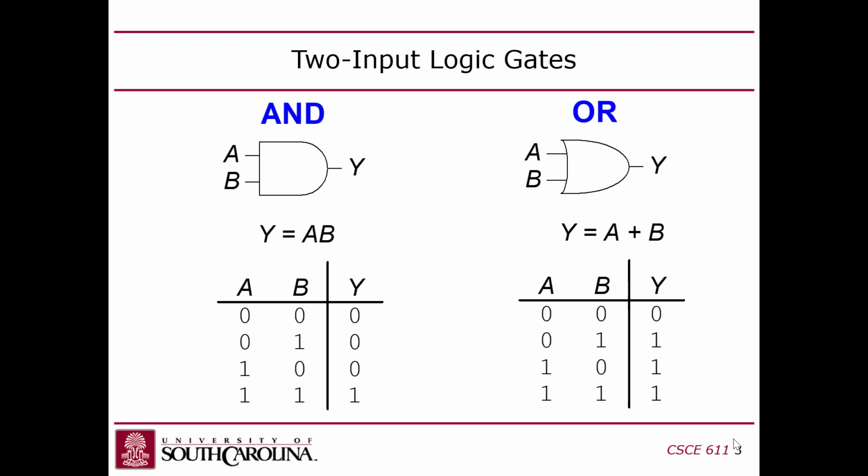You can make any kind of gate you want, right? Now these AND and OR gates just define the specific truth tables for these guys. But you could put any value in this output column on an FPGA and get a reconfigurable general purpose logic gate. You guys with me? Makes sense? So a LUT can be built into 2 raised to the 2 raised to the 7th power possible gates. So 2 to the 128th power. That's an astronomically big number. And that's just one LUT on an FPGA. Those are the possible gates you can build from that.